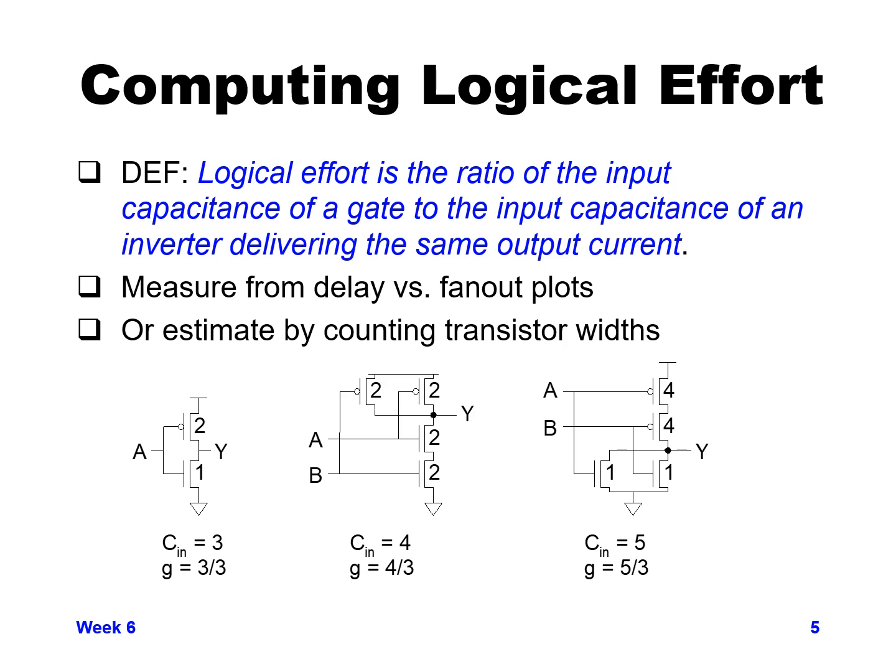So in computing logical effort, first of all we need to know the definition for logical effort. The definition: logical effort is the ratio of the input capacitance of a given gate for each input to an inverter that would be delivering the same amount of current, so the same equivalent resistance as an inverter. So we need to look at what the input capacitance of the gate is and then divide that by the input capacitance of an inverter delivering the same amount of output current.